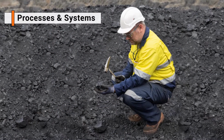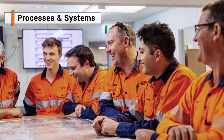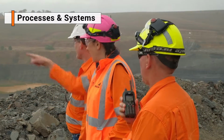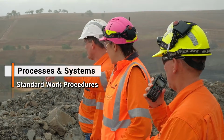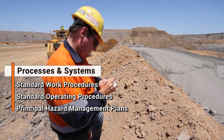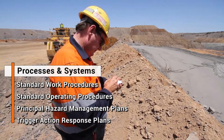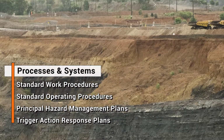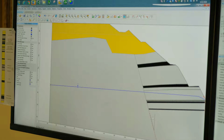Mine sites must have in place processes and systems that outline roles, responsibilities and management plans to identify and control geotechnical risks. These may include standard work procedures, standard operating procedures, principal hazard management plans, and trigger action response plans, commonly referred to as TARPs, outlining the minimum actions and responses for normal and elevated risk states relating to geotechnical hazards. All slope designs should have an appropriate factor of safety or probability of failure.